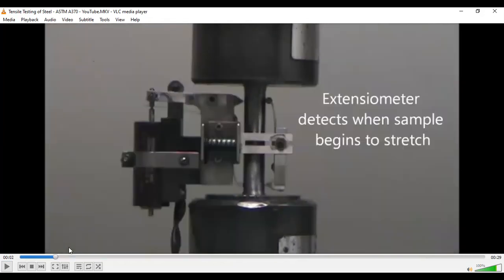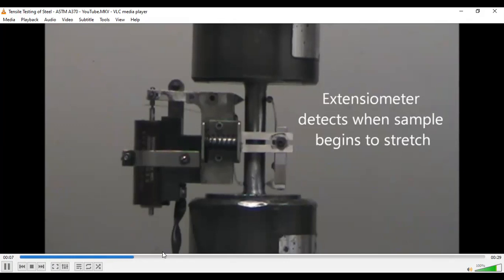So what is Young's modulus? It is the stress over strain. I mean, how much force is applied and how much was the deformation. Overall, you can summarize this: it's the stiffness of the material. So at what force, how much it can deform. And this is important because we are dealing with very long drill strings, which have a lot of weight and forces acting on them. So we take care of tensile. Otherwise, our pipe can break and so on.